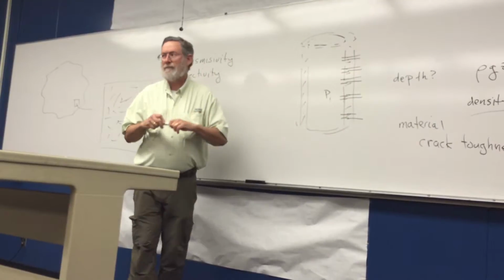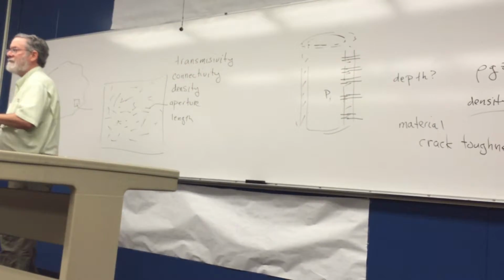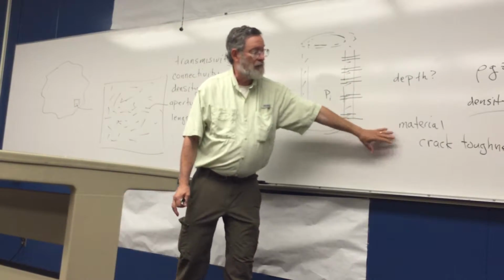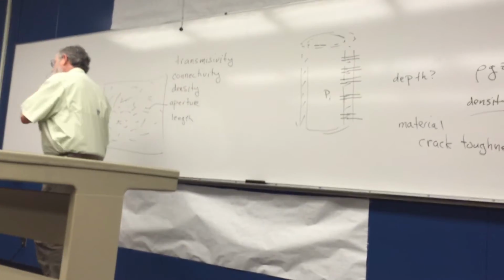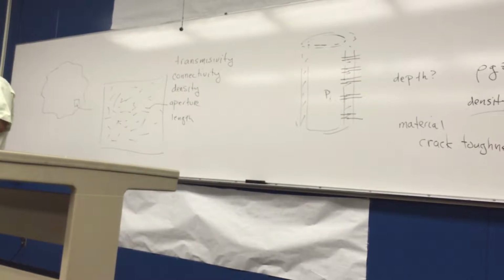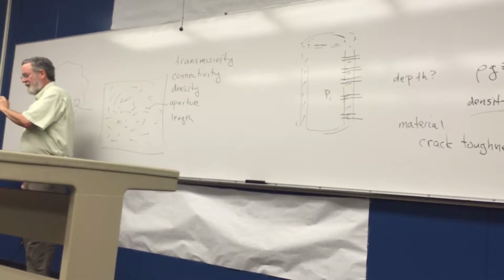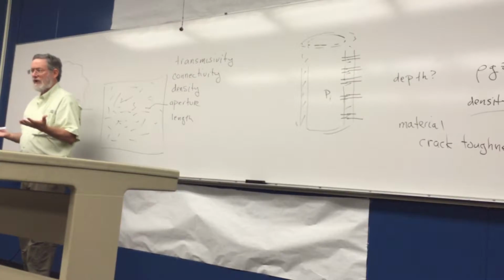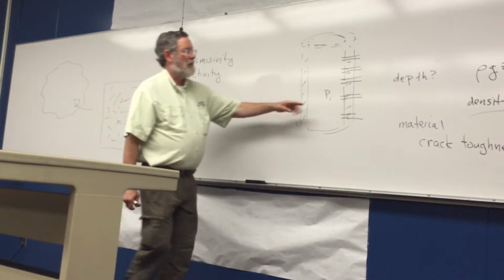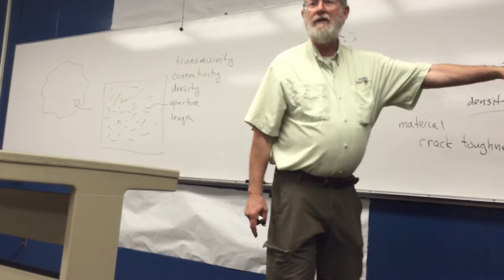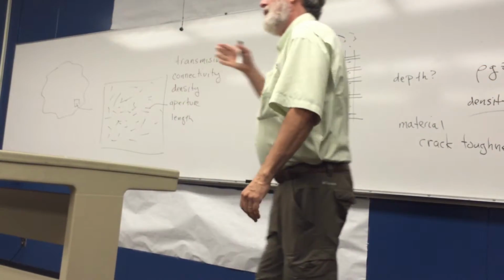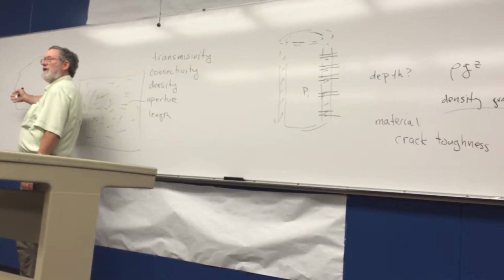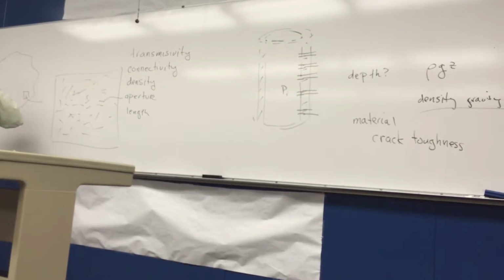Would you also look to see if the material is more elastic, like mud? Well, here we would look at the material and we're treating it, in the most simplistic case, as an elastic material. But in reality, we're thinking of it as a poroelastic material because we're going to have fluid bleed, we're going to have pressure drop off. So we want to know what sort of internal pressure we need to start the fractures and to propagate the fracture far enough.